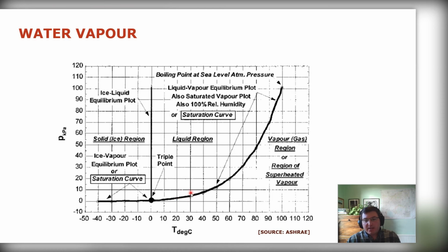So basically what that means is that for any temperature that you have, there will be a certain amount of water vapor that is natural, so to speak, that wants to evaporate to get into equilibrium, and it wants to reach this partial pressure of water vapor inside this volume to be equivalent to saturation. And once that's reached, we're in equilibrium, and nothing is evaporating or condensing. Or to be more accurate, the amount evaporating and condensing matches each other, so there's no change in overall balance.